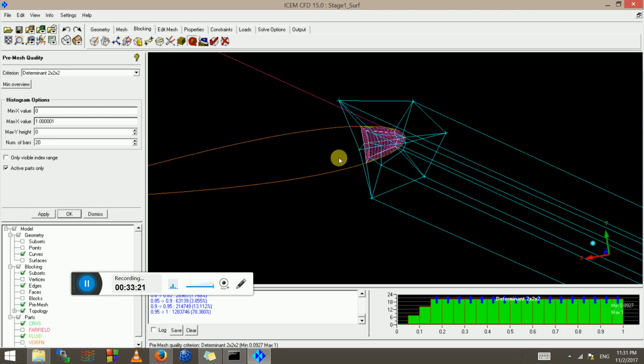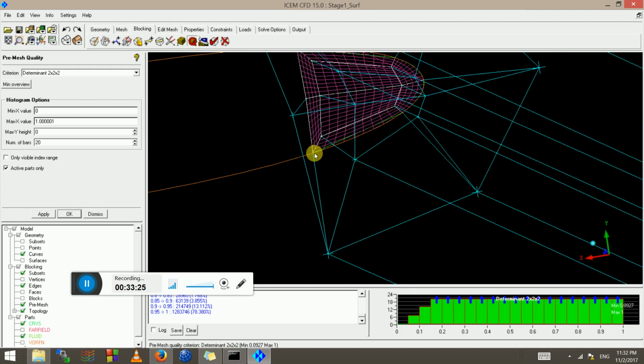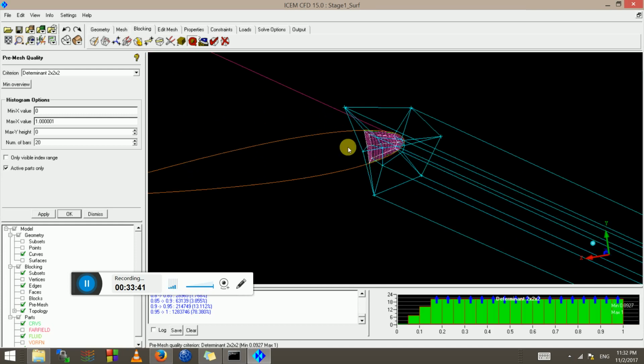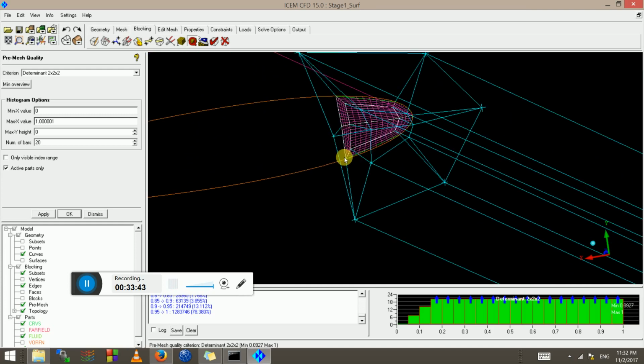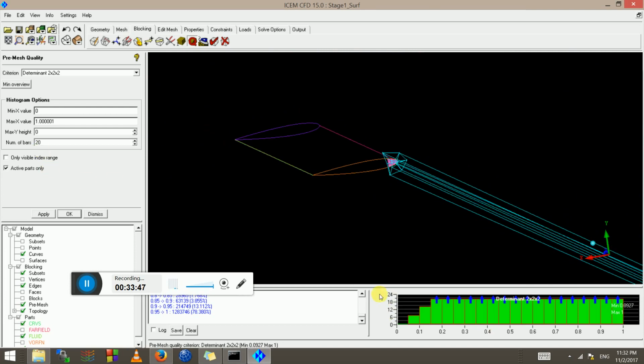That's how you move the points and play around. If I pull this one up in the Y direction, it will be more appropriate, because this block will then have a better shape, since it's a bit distorted here. So you have to think about how the blocks are formed from the edges and try to make them as square as possible. And I'm just going to click done.